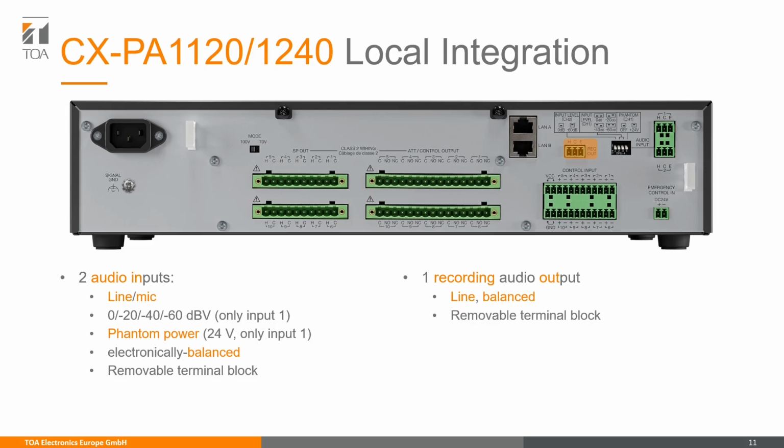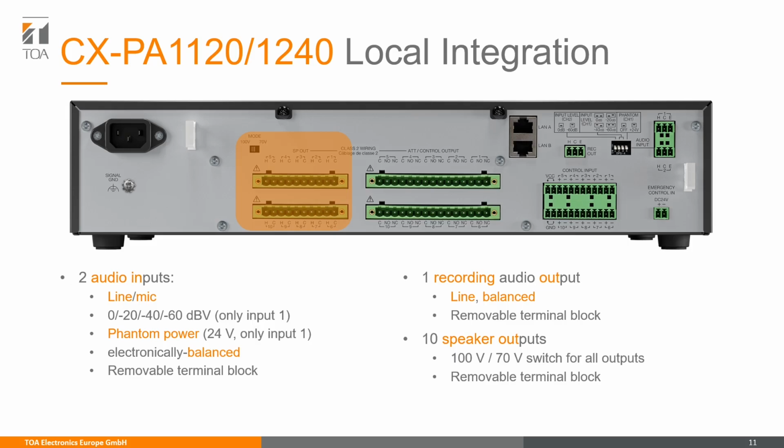Of course, here we have our 10 speaker outputs. For the speaker outputs, we have a selector between 100 volt and 70 volt. Because this switch affects the amplifier, this will affect all speaker zones at the same time. And again, the speakers can be connected via terminal block.